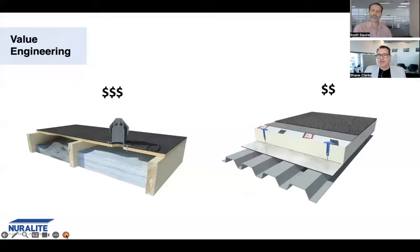So what we're comparing in this slide is that the Nuratherm warm roof on metal tray system, if you look at the whole thing holistically, including the metal tray all the way up to the membrane, is a lot more economical than a traditional standard cold roof, believe it or not. My experience sees a lot of cost actually goes into the construction of the timber. And obviously timber prices have risen, etc. And there's a lot of timber and a lot of time which goes into that structure. Whereas, like Scott touched on, that metal tray is incredibly economical and fast to install.